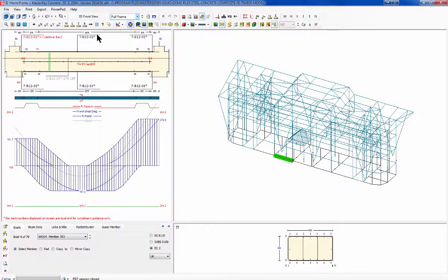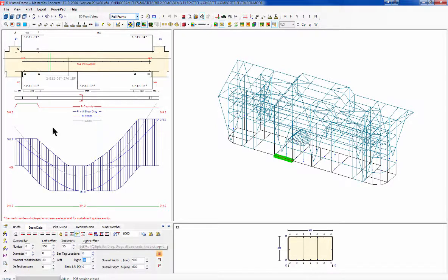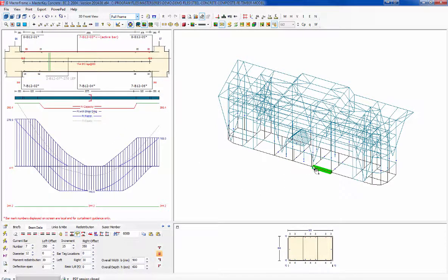So it's very straightforward and easy to use, and again we just need to run through with a design. We can also, if we want, take some bars out and then it'll automatically lap across here. If I use my lasso, I can take that lap and just put it nice and neatly in the middle of the structure somewhere smart and intelligent, and we're not using as many bars. So we have full access to the full reinforced concrete design in our frame.